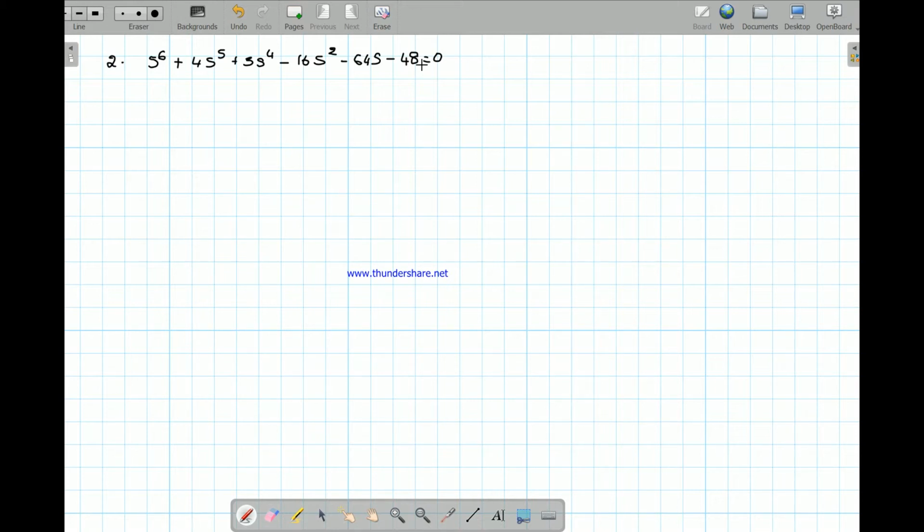You need to find out whether it is stable or not by finding the number of sign changes. In the earlier problem, we did not see any sign changes. We found the range of values of k for which the system is stable. So within that range of k the system is stable. If k is less than 0, or if k becomes greater than 3.36 in the previous problem, the system would become unstable. Let us see what condition we will see in this particular problem.